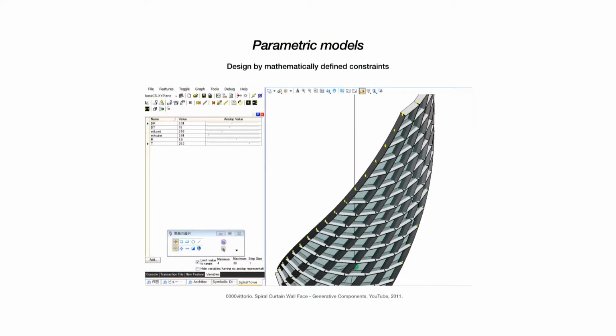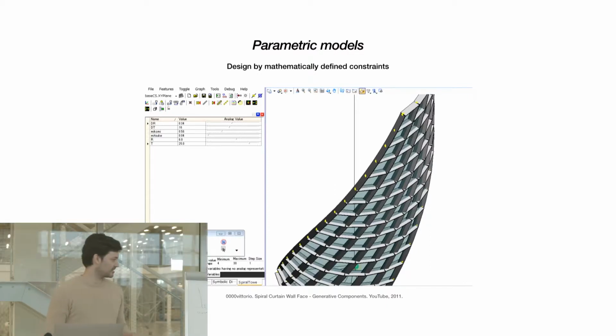And in this way, you can create efficient libraries of these components. For example, the constraints you can have would be to align, for example, points, axes, surfaces, or tangency. Yeah. And these relations are always described as algebraic equations. And you need to solve the algebraic equations to see what the limit of a certain parameter is.